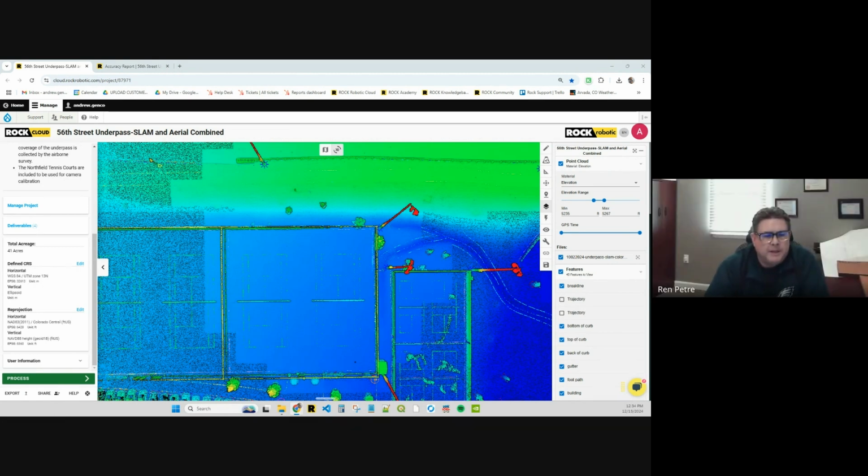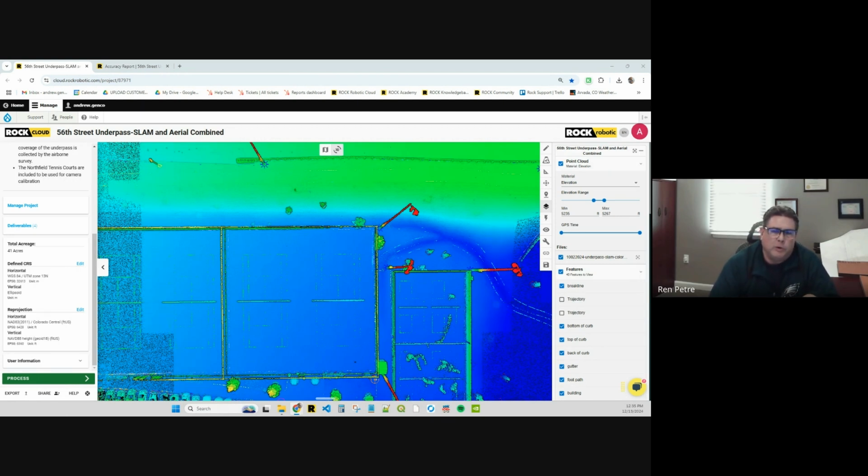It was more of, you have a great 3D representation. When you get the contours or the surface back, I know sometimes it wants to hold the road on the very top, and then other times it will want to map like the box culvert or the bottom of the ditch, and then it shows the road coming in and following the ditch as opposed to staying with the road. I know with Civil 3D, it's tough to have two surfaces, one with a bridge and one with the swale below. If it's a box culvert, it's always easy because we can just show it as hidden lines. I didn't know if there's something that's worked for you in the past in trying to get those deliverables.